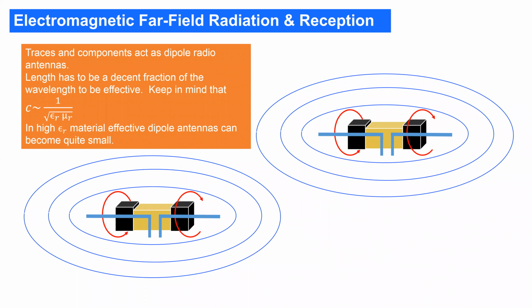These additional coupling mechanisms would be, right out, electromagnetic wave creation, like an antenna, so that you have parts which create an electromagnetic wavefront and couple directly, like an antenna, into the other. But for that, it's necessary that the component size has to be in the order of the wavelengths, so lambda divided by 2 or lambda divided by 4. Most times the parts are pretty small against the wavelengths we are interested in.